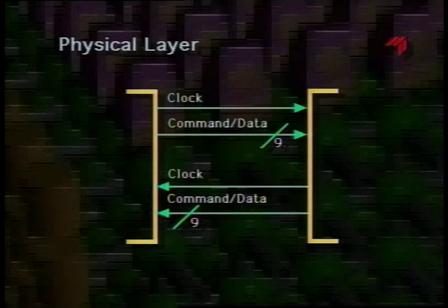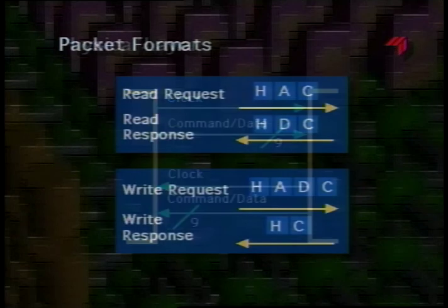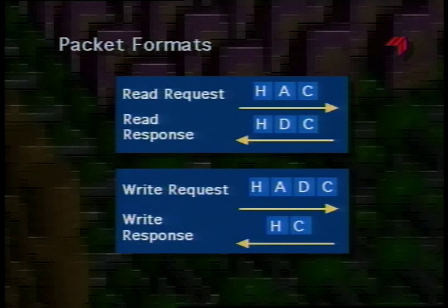The point-to-point connections give excellent fault containment and isolation and make it very simple for hot pluggable design for online service. Also, sending a clock along with the data and resynchronizing it at each end means that we don't need a global synchronous clock. That would be very difficult to implement in a network where there are a large number of distributed components. This diagram shows the basic packet format.